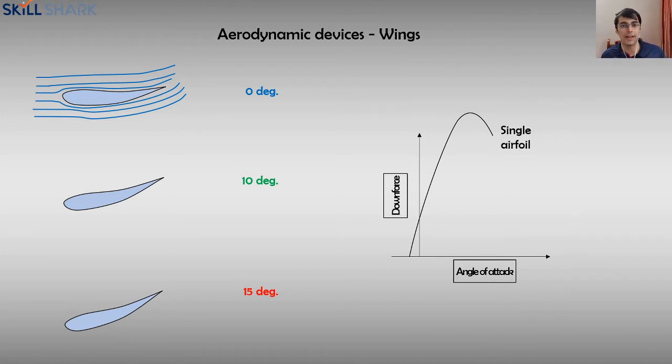Now this is very complicated when you look at the actual equation, so we won't get into that. But for now, take it for granted that airflow underneath that airfoil accelerates and goes faster than the air above. So because of that, faster air means that it has higher dynamic pressure, but it has lower static pressure. Slower air on top has higher static pressure. So you have a pressure differential that goes across this airfoil and presses the airfoil downwards. That's what happens at 0 degrees. As you can see, that is this intersection point on the graph.